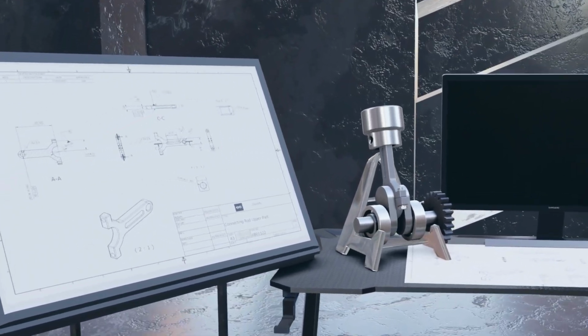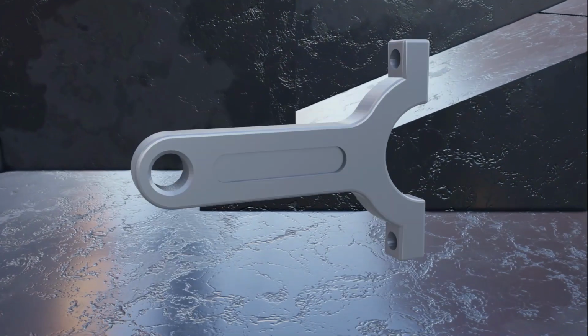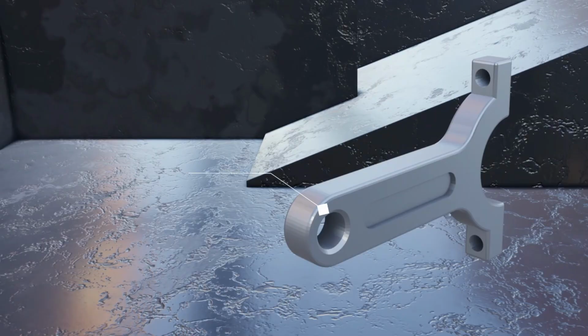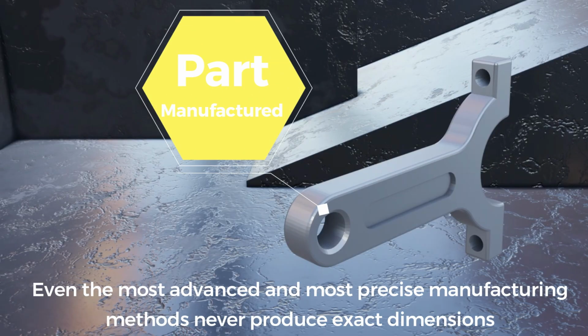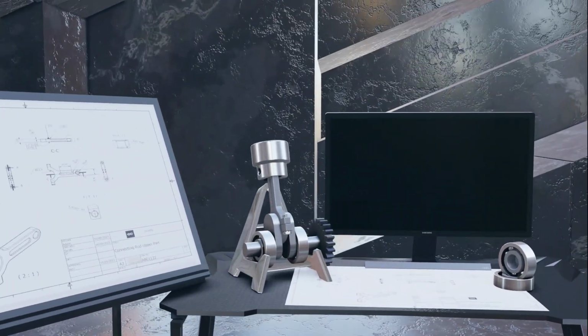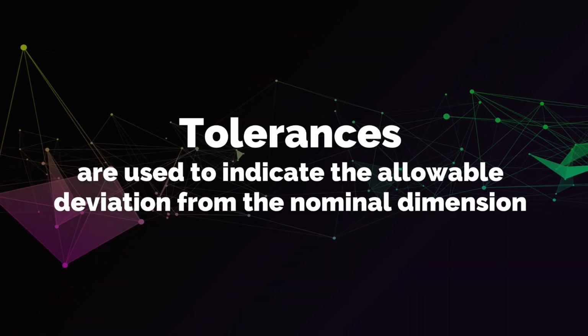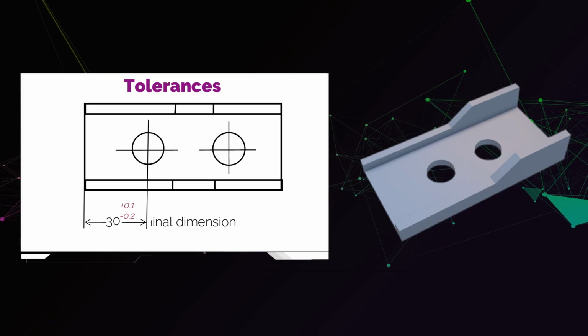Now, as we have seen in the introductory video, parts are manufactured according to the dimensions given on the drawing, but manufacturing methods produce parts that meet the required dimension with a certain precision, but never with 100% precision. Even the most advanced and most precise manufacturing methods never produce exact dimensions. There is always a deviation. It's up to the designer to specify the allowable deviation that the manufactured part can have in order to still be accepted. In other words, tolerances are used to indicate the allowable deviation from the nominal dimension. The nominal dimension is the dimension value given on the drawing.